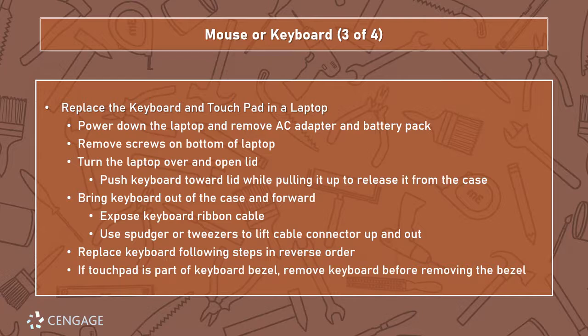If you're dealing with a ribbon cable, traditionally it's going to be connected to what's called a ZIF connector, zero insertion force. We talked about these a little bit with CPUs. The ZIF connector for a keyboard is a little bit different. It's still the same idea. We're applying force evenly across the socket so we don't damage any of the pins or connectors. In this case, there is no real connector other than pressing the cable by means of the leverage of this little slot into its connector points. It's going to be little contact spots.